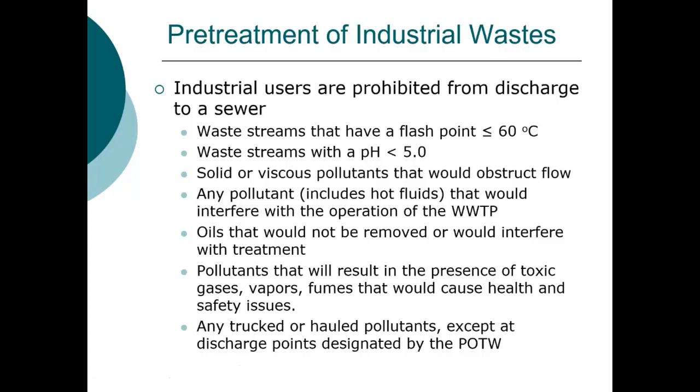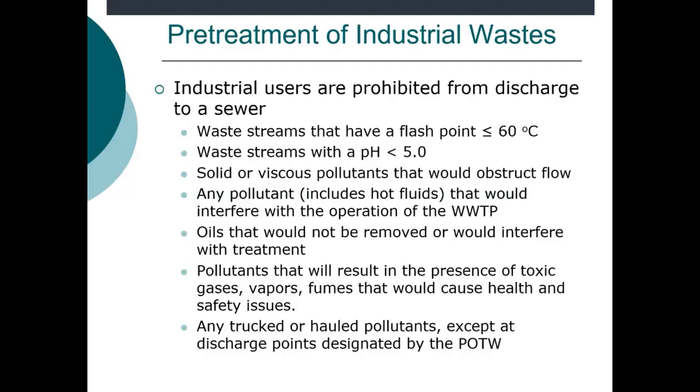So, for instance, there are requirements regarding the flash point. You don't want to release pollutants that can react, can explode, especially if you're producing hydrogen sulfide. There is a significant potential for an explosion. You don't want waste streams with a pH of less than 5, and this is because of corrosion.